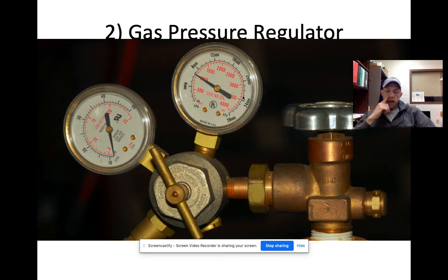And then that whole volume of the cylinder is filled with that much pressure at this particular moment. The other gauge on the left on this particular regulator, we've got an increment that tops out at 35, and then we have 50 on the outside, CFH. Most of the regulators that I see, they're both PSI and bar. This particular one's using kilopascals.